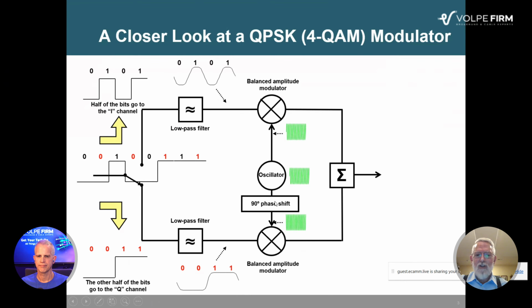And then this way, the phase is delayed 90 degrees. So there's a 90-degree phase shift. So it's the same RF signal, but here, this second oscillator output is delayed 90 degrees. So we say that 90 degrees is in quadrature. So this is the Q channel. That's why we call it Q. So these two signals, this is a sine wave, and because this has been shifted by 90 degrees, we can call it a cosine wave, but basically a sine wave with a 90-degree phase shift. So these two go to these two modulators. So this is the feed into the modulators, and then we've got the baseband data going into the modulators, and the baseband data modulates this sine wave, and the baseband data down here modulates this cosine wave.